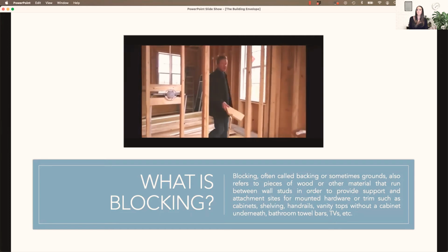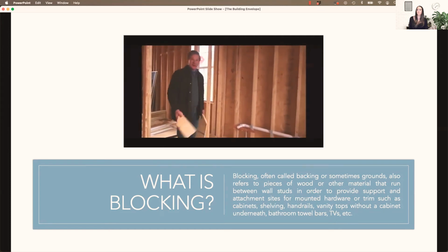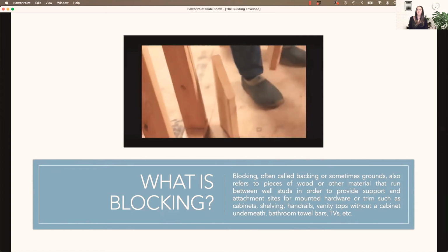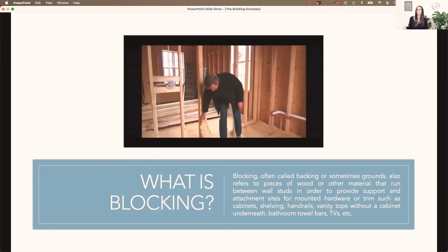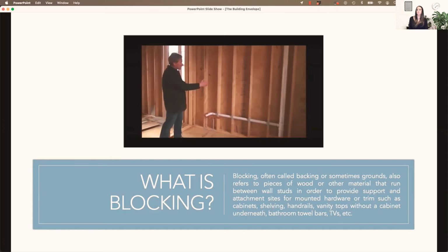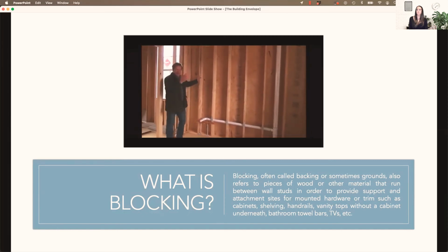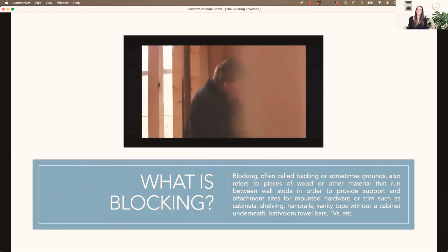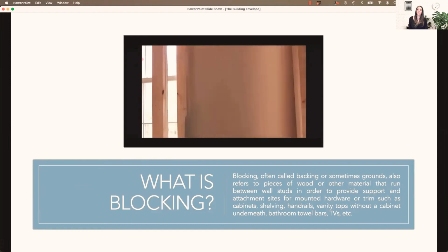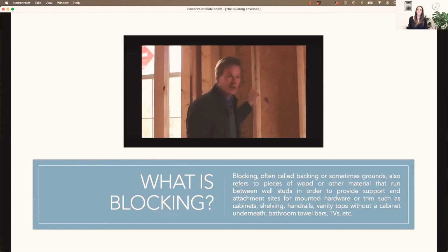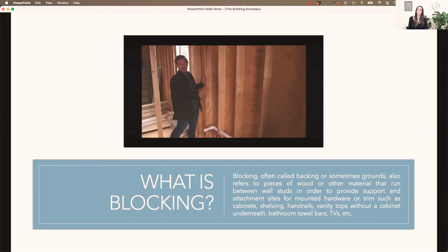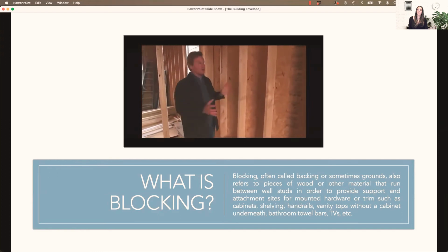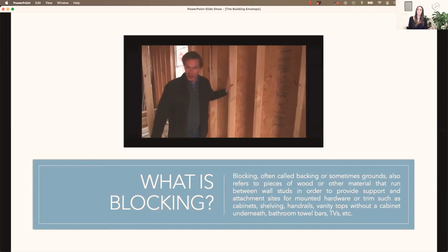So this is the master bathroom, and we've already figured out where things are going to go. You can see by the plumbing indicators, this is going to be where the shower goes. Over here's the potty, and over here's going to be the vanity. Knowing that, I'm probably going to have some sort of mirror unit here over the vanity. I'm not sure what it is. So this is one of those situations where let's go ahead and shore it up, because we're using the scrap material anyway. It's going to be thrown out, and applying it to these walls is going to make the finished work in here so much less frustrating when we know where we can attach something to a solid wall.